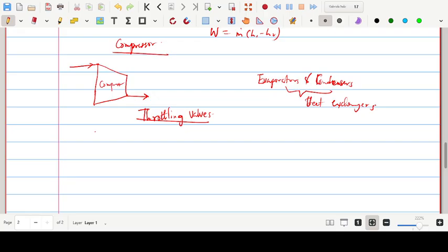But here now, apart from the compressor, condenser and evaporator, the other one we have is the throttling device, which is generally called an expansion valve or capillary tube. It is a tiny valve. Majorly its purpose is to cause a pressure drop, because the pressure coming in is at high speed. The purpose of the throttling valve is to reduce the pressure, so it will cause a pressure drop. You understand now? The diagrams I've considered, you have to master them.